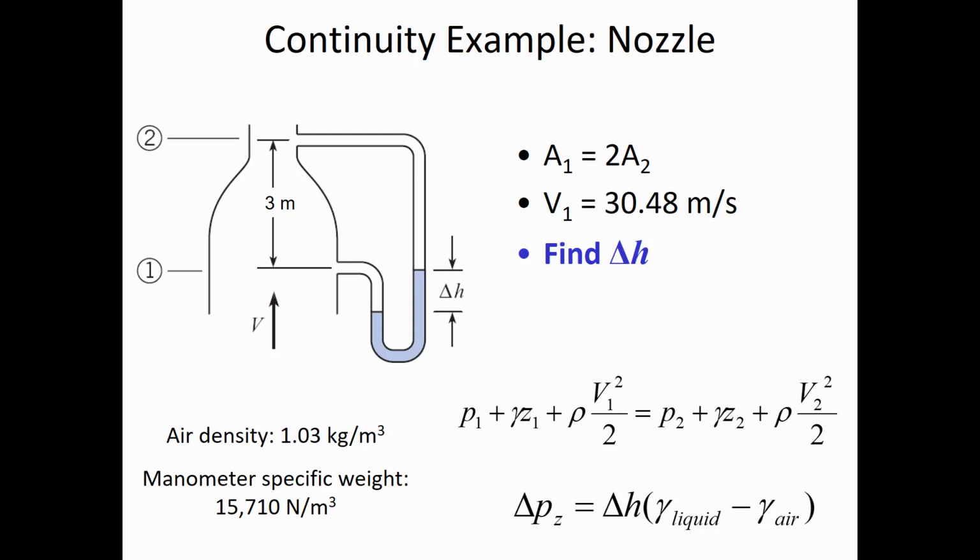1. And what's the clue that there's more pressure at 1? Yeah, if there wasn't more pressure, it'd be the same. But there's an imbalance there. That means that there's more pressure at 1. Now, the question is, does that match what Bernoulli's equation tells us? Bernoulli's equation says that if the velocity increases, the pressure will decrease. And that's what we see. All right, so all is right in the universe. The manometer kind of is behaving the way we'd expect it to behave based on Bernoulli's equation.